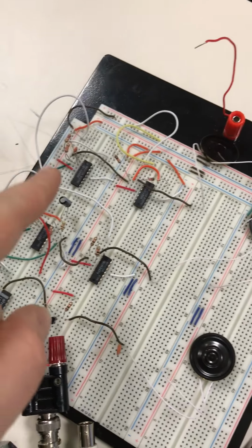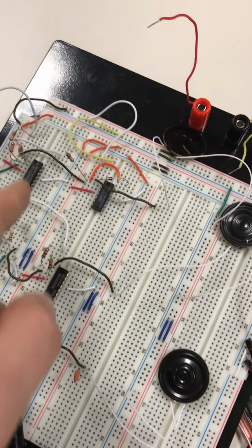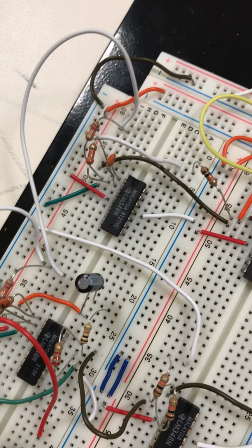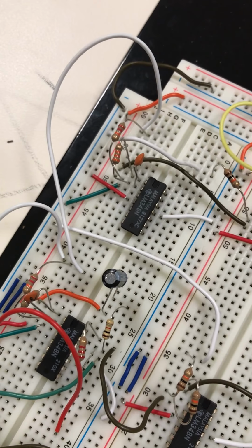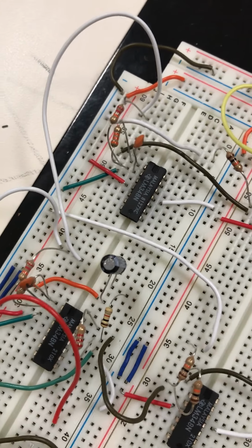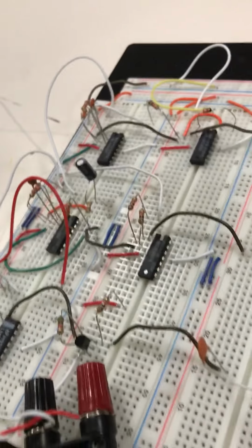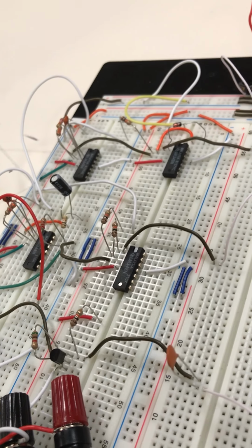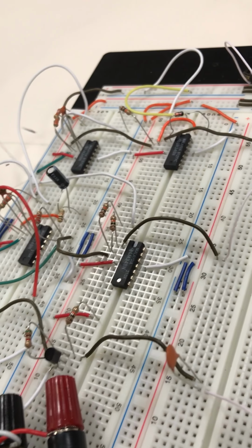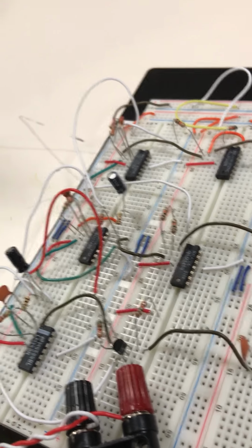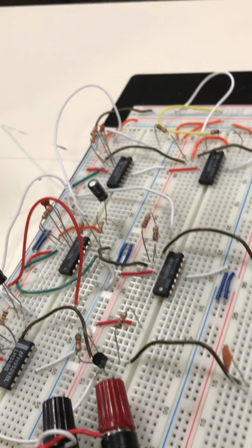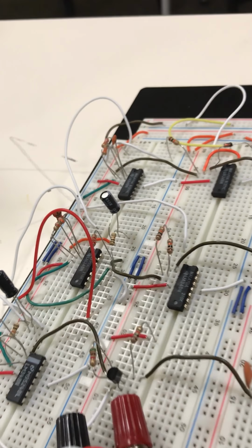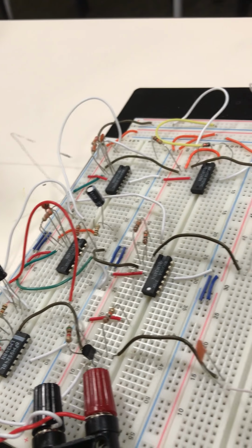We're going to start on this side, and you can see we have our low pass filter right here. This is an active low pass filter. As you can see, it uses an op amp. Based on our resistor values, we calculated the gain of the op amp to be approximately 3.5 and the 3 dB cutoff to be approximately 7 kilohertz. The reason we chose our 3 dB cutoff to be about 7 kilohertz is because the human ear can hear up to about 20 kilohertz, so we want it to cut off before the human can stop hearing it.